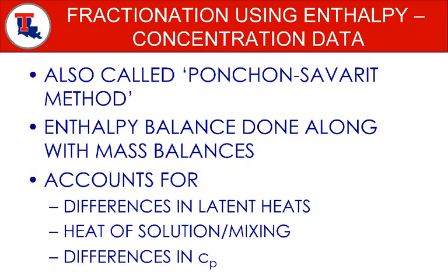Across each tray, you're doing an enthalpy balance, right? Because across each tray, the enthalpy lost by the liquid stream will be equal to the enthalpy gained by the vapor stream. That's the best way to make a heat balance. So it accounts for differences in latent heat, heat of solution, and mixing.